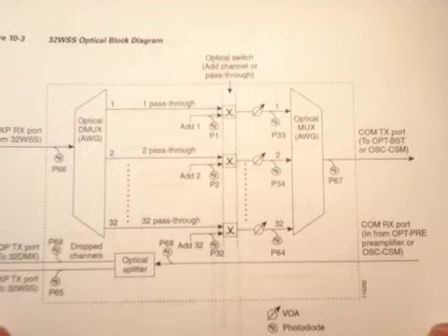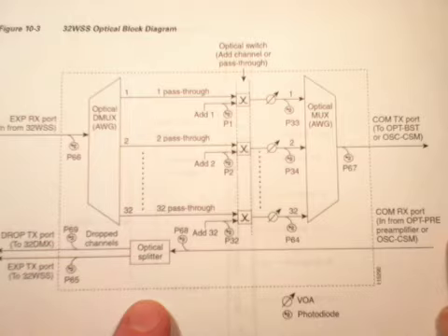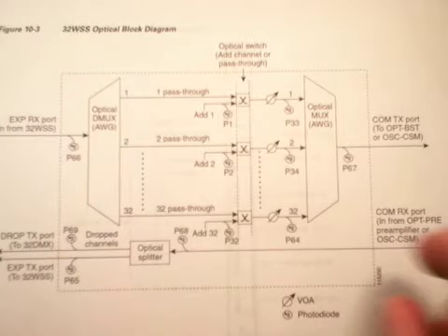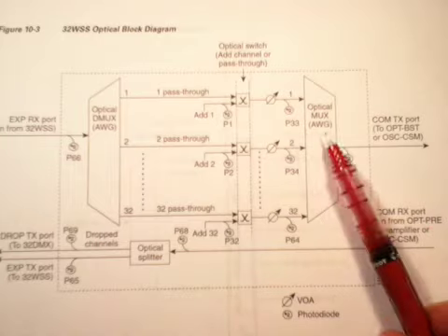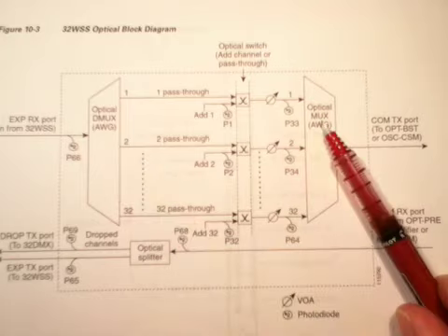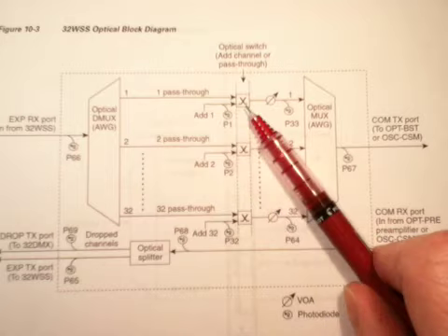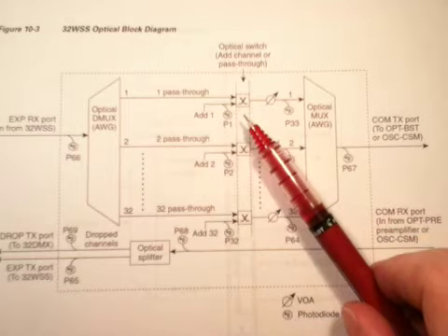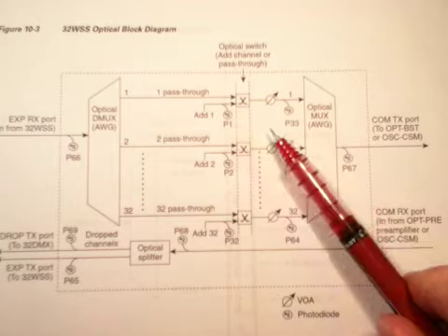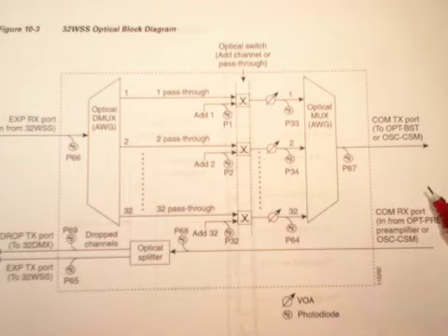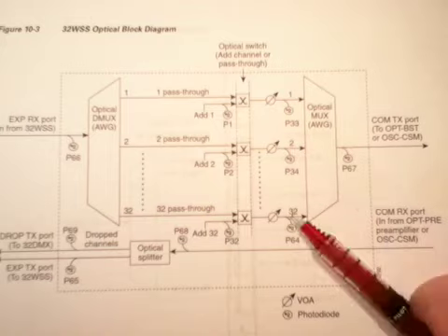one I feel is this 32 or 40 channel wavelength selective switch, in which we have two arrayed waveguide gratings, two AWG devices facing each other. One is a DMUX and one is a MUX. And in between we have the ability to add channels using 1x2 switches, to monitor the power on the add channel using photodiodes, to have VOAs on every channel, variable optical attenuators, to equalize the powers, and also photodiodes to measure those powers as we go.